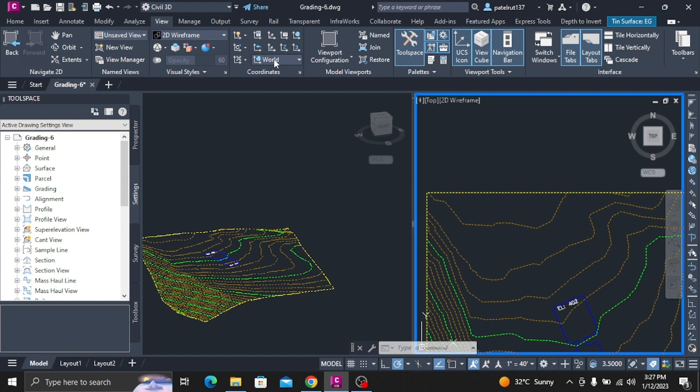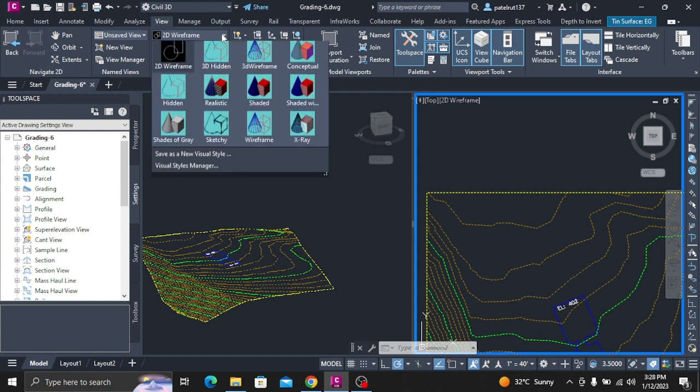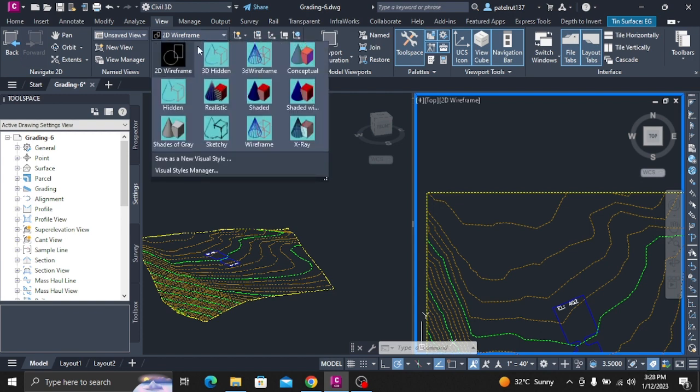Click the original, interior feature line, the blue building pad. Press Enter. Press Enter again to select the default displacement selection. Press Enter again to accept the default displacement of 0.0000, 0.0000, 0.0000. In the left viewport, notice that the triangulation of the arcs along the ramp has improved.